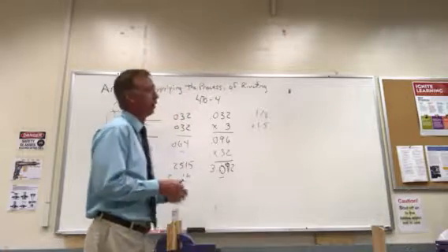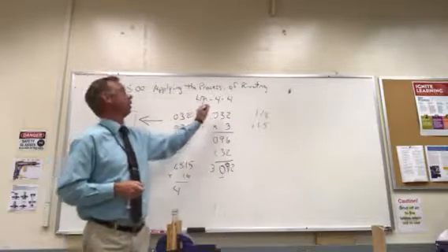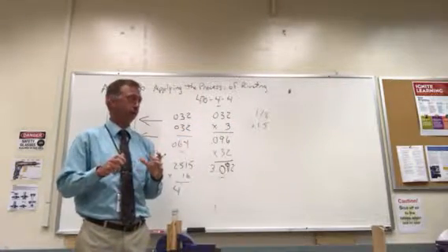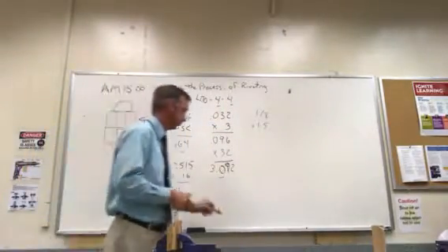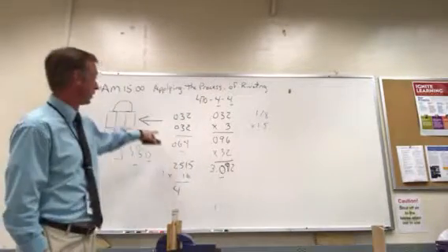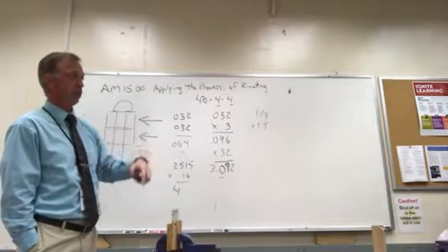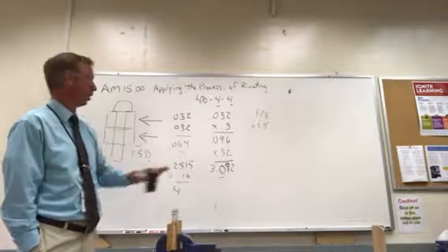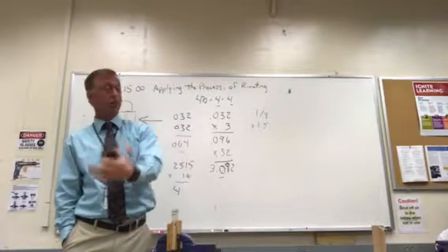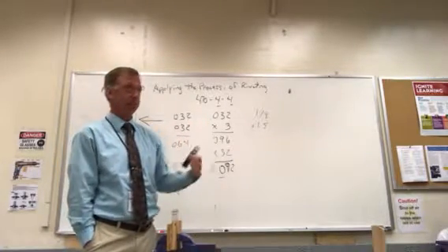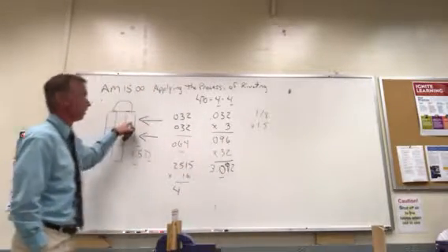So now what we end up with is a 470-4-4. Once again, this first 4 was what? The diameter, good. And the last 4 is the what? The length, good. Does anybody have any questions on how to find it? Once again, we struggle just a little bit. The diameter is found by the thickest piece of sheet metal times 3, and that gives us the diameter of that rivet. In good situations, we can just pull it off the paper, our spec order or engineering order, which tells us the size of rivet. Otherwise, multiply that by 3.